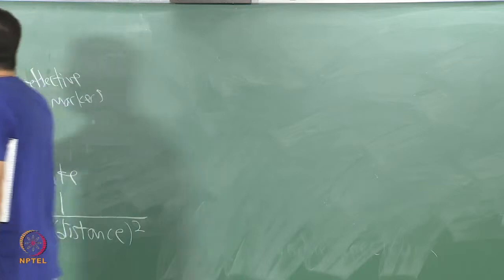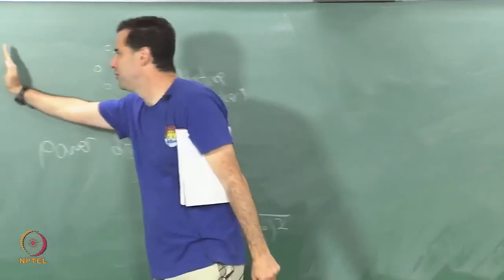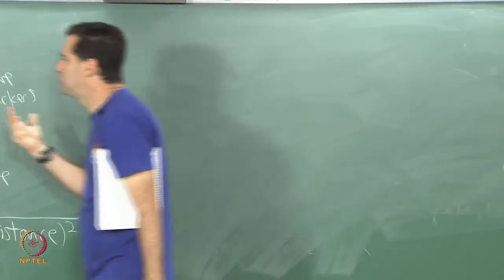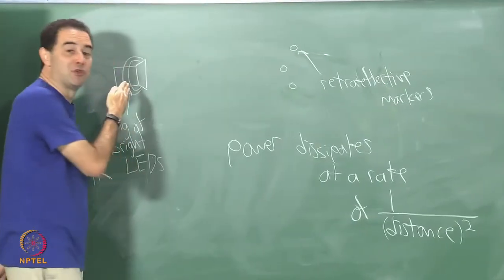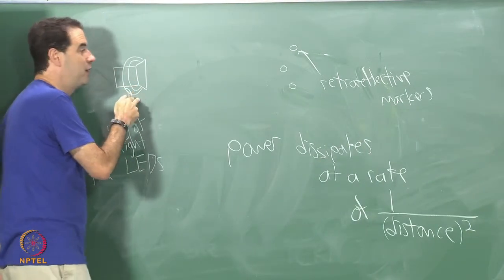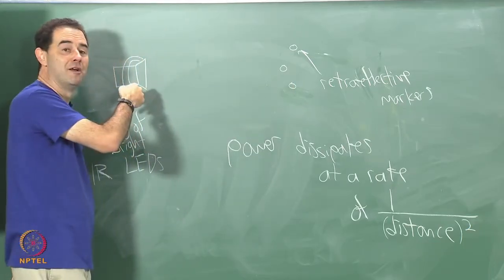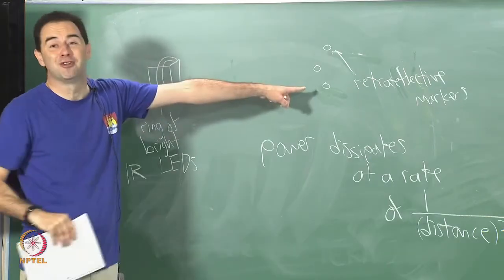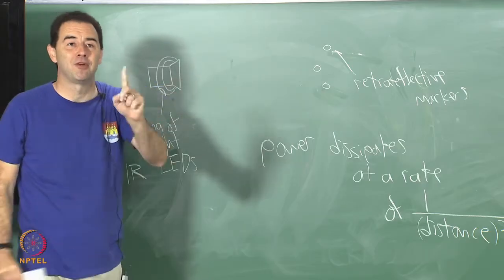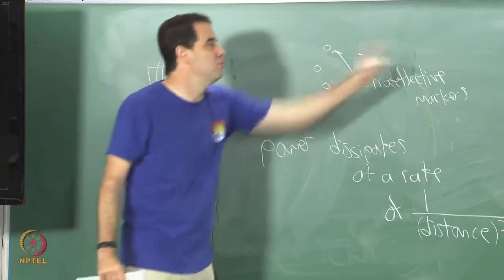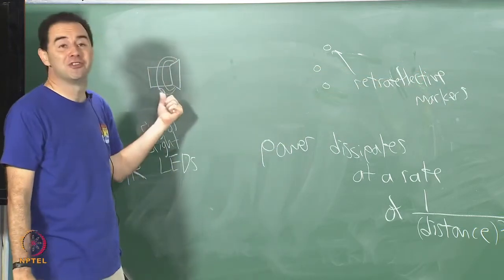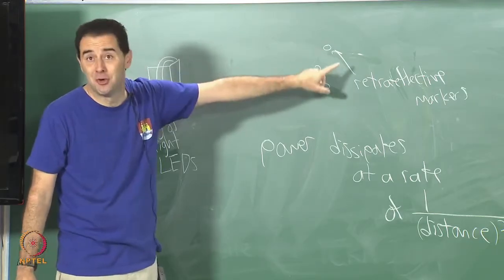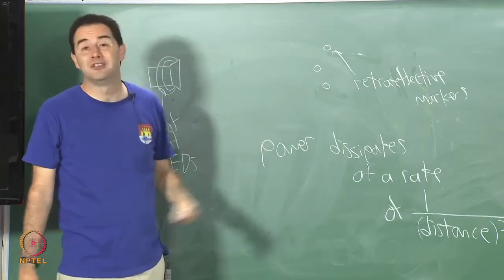And so the further away you move these, you get a lot of power up very close. The further away you move, the lower it gets. And you have to get the light to essentially travel twice the distance, right? It has to travel from the ring to the marker and then from the marker to the camera. So you have double the distance. So one possible improvement is to just put the light directly on the markers, right? If I can directly light the markers, I've cut the distance in half, right? So that means I should be able to move the markers further away and get the same amount of brightness in the camera. If I don't mind putting batteries or whatever I need, or this has to be plugged into a separate source. If it's on a headset, then I have to power these lights.